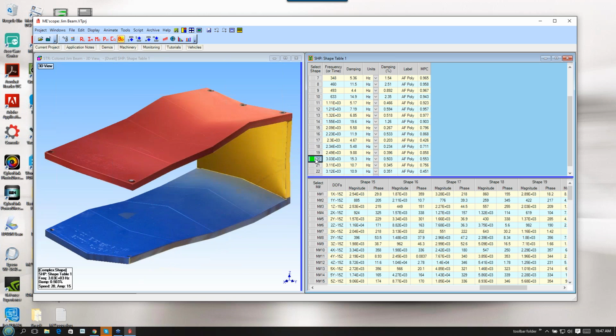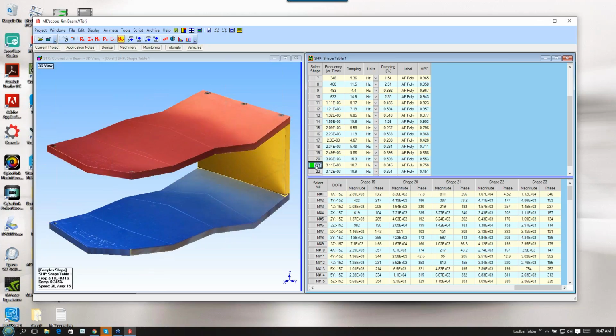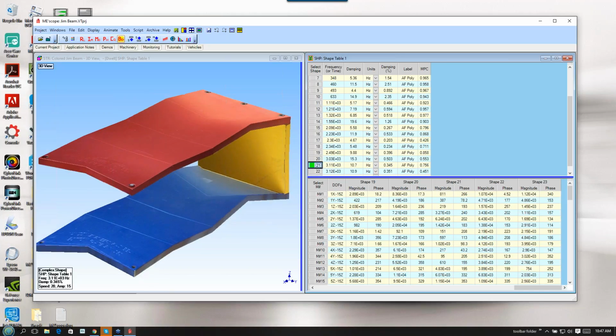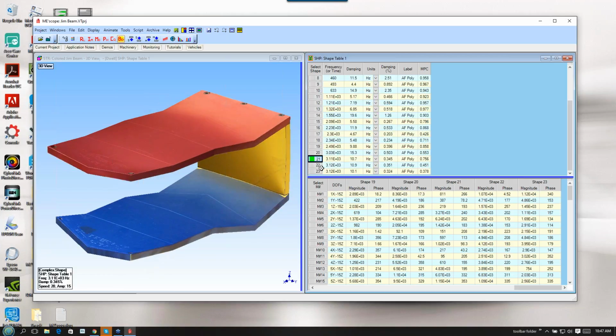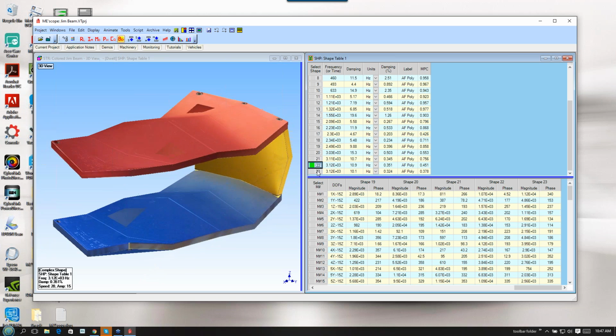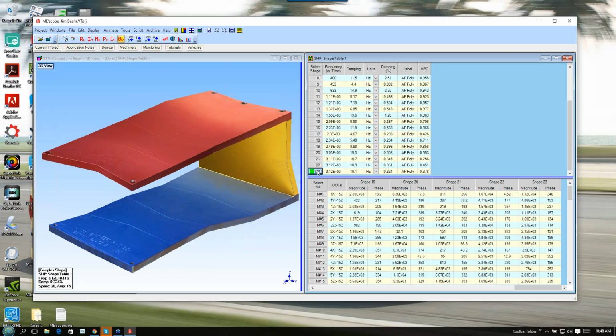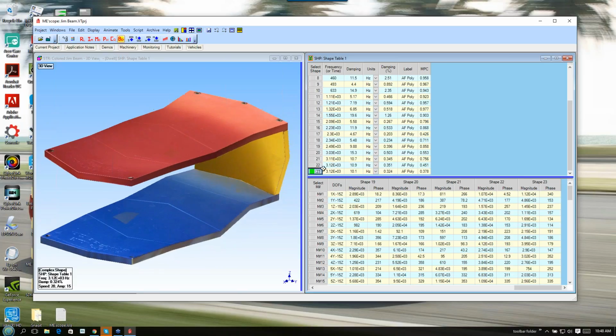Again, as you get familiar with your data, you can see that what this global fitter is doing here when I've got mass loading, it's doing the best job it can to fit these high frequency modes, but they all have mass loading in them. And see, here's 2 of them right here at the same frequency, almost the same damping.